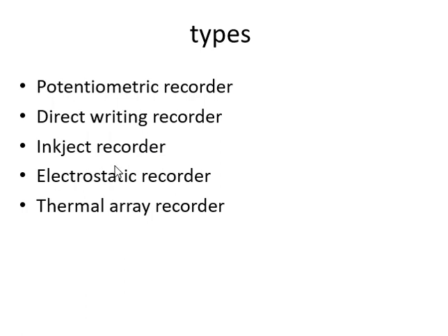Inkjet recorder. The recorder has a glass capillary tube placed between the poles of an electromagnet. The coil of the electromagnet is connected to the amplifier of physiological signals. A small cylinder magnet is attached to the ink capillary tube. Electrostatic recorder consists of an imaging or writing head, a toning head containing positively charged ink particles, and a vacuum knife.